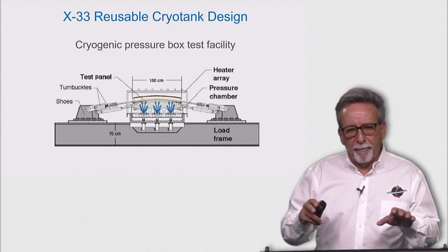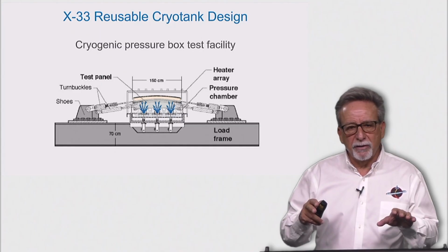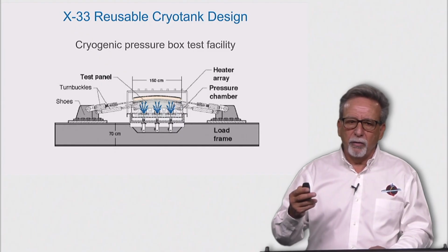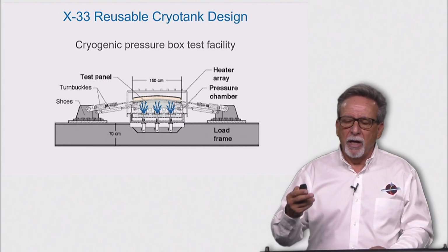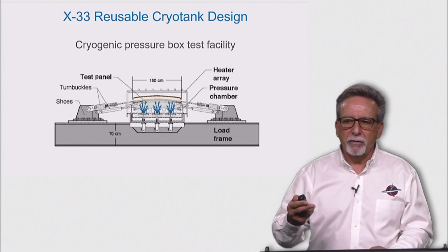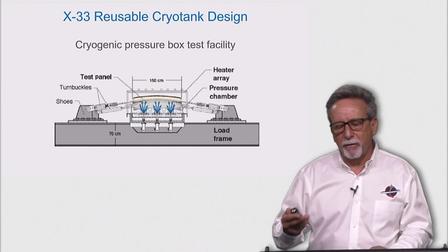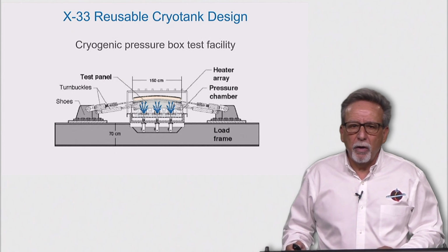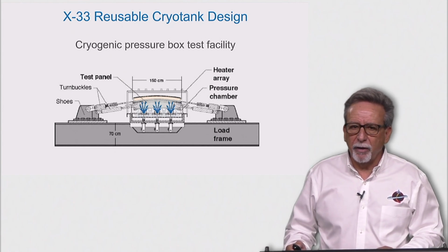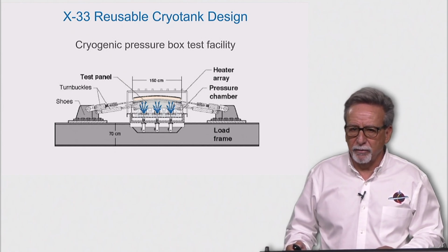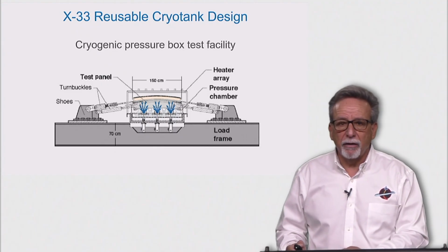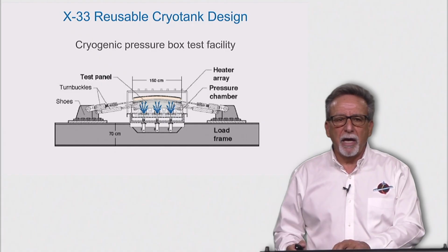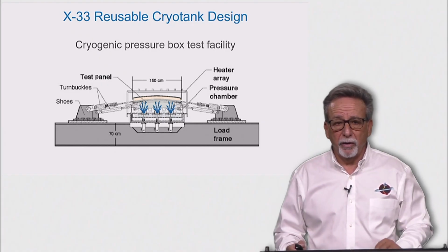Curved tank panel concepts can be tested in this facility at a relatively low cost compared to full-scale tank tests, in order to evaluate the feasibility of these various tank constructions, their attachment to TPS material, etc. We designed and had built a new test facility, the Cryogenic Pressure Box, or CPB test facility, in order to validate full-scale tank subcomponents under realistic static and thermomechanical and pressure cyclic loading conditions.